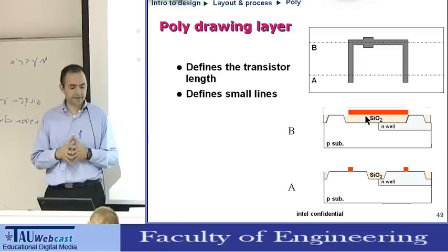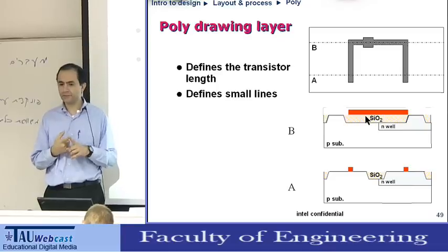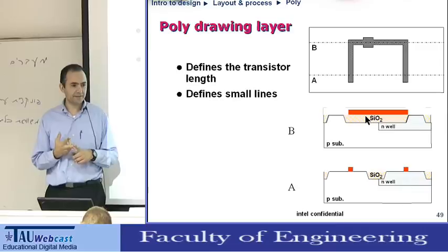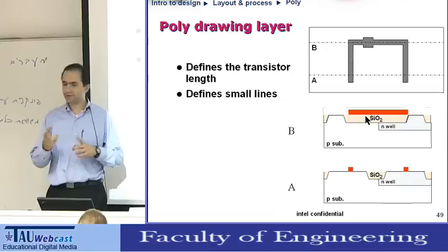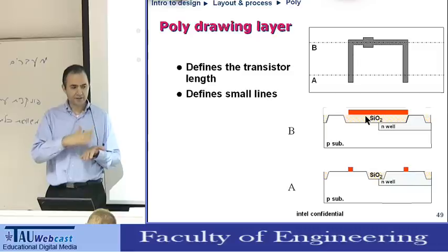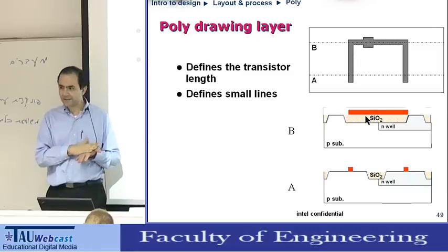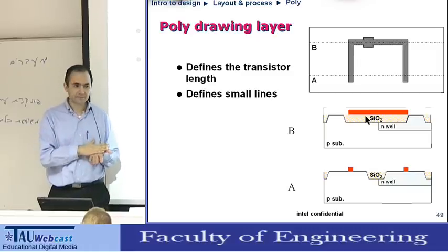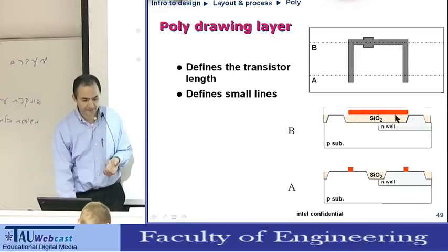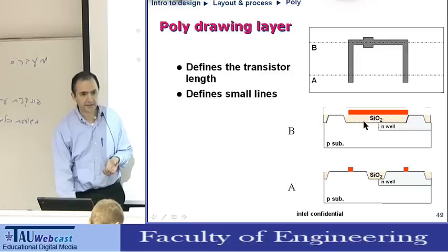What steps will we use? The first one will be breakthrough etch. The next one will be, we want to etch silicon, okay? Silicon etch, either a fast etch or not a fast etch. Then we're getting close to the, what do we have below the silicon? The oxide, the gate. Okay, so we have the gate on the active areas and we have oxide on the isolation areas.